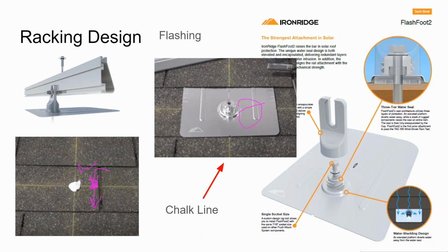So what I do is start out and go in and try to identify all the rafters going across the rooftop. Then you can measure to see if your markings are regular based on the rafter spacing you've measured inside the attic, and that can guide you on if you're off or not.